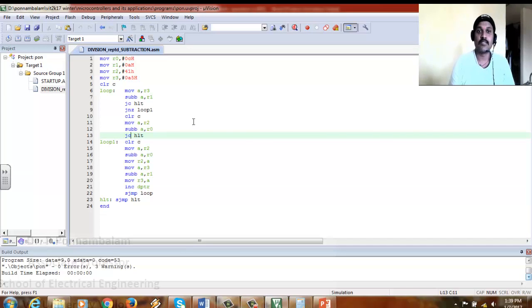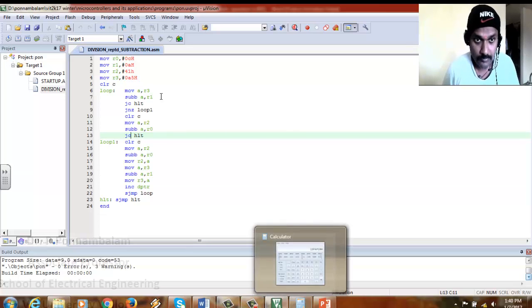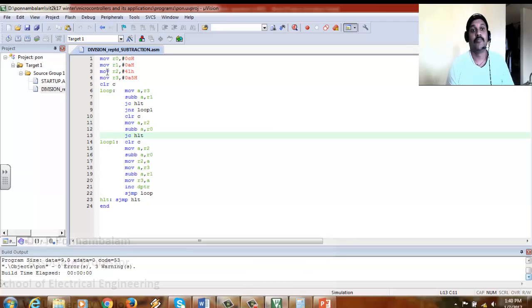So this is 16-bit division, in which you can see we are dividing the number A541 by 0A0C. In this case, as we have done in the previous cases, we are initializing the numbers with R0, R1, R2 and R3, but in the previous case we had a different fashion. Here the fashion will be this way: R3 is the upper byte, that is A5 of the numerator 41,